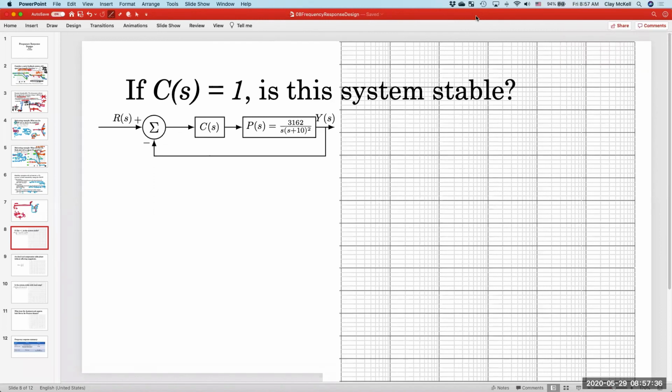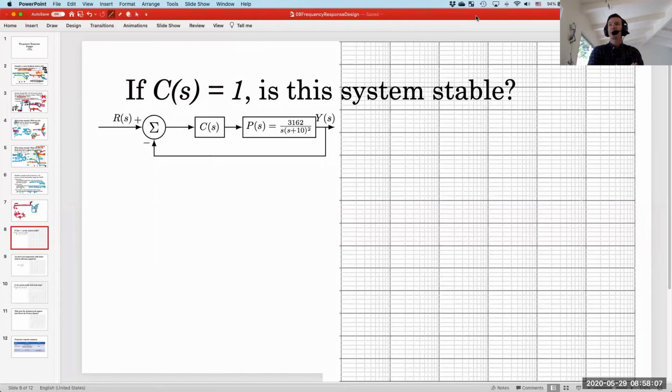I've been wondering, for the telescope, I had been working on making a better controller, and then I realized after a while, I had basically just made a new PID controller, but that was in series rather than those 3 parallel branches. Is that a bad thing to have them like 3 op amps one after another just for the 2 zeros and a pole at the origin? Practically speaking, yeah. So whenever you get 2 zeros and a pole at the origin, you're right. That is a PID controller.